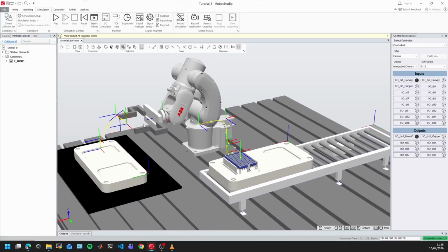For example, I can make one box in here, and if this base collides with that box, let's imagine the box is a sensor. If something collides with that sensor, do something. To do a collision, let's go here, create collision set.